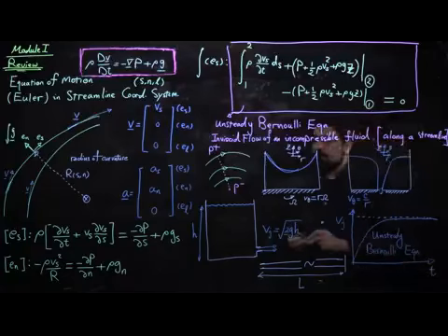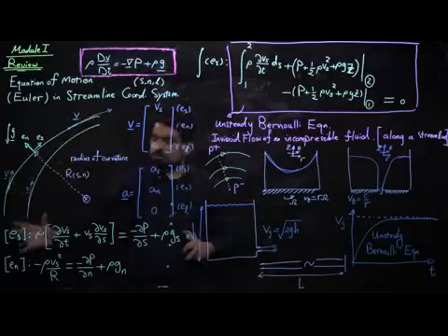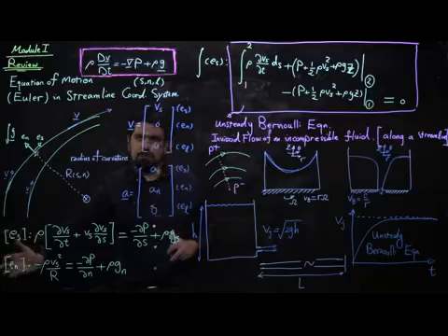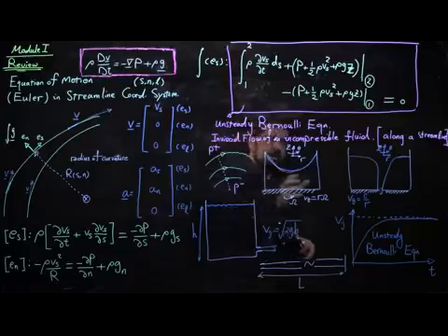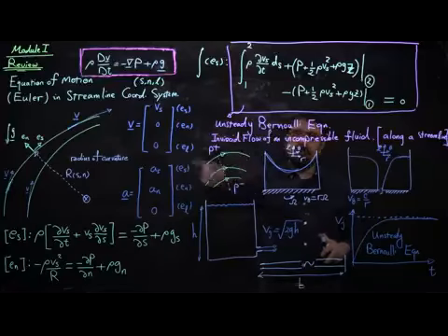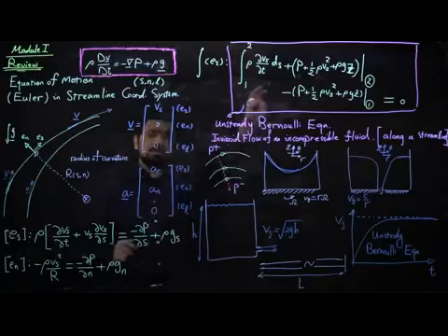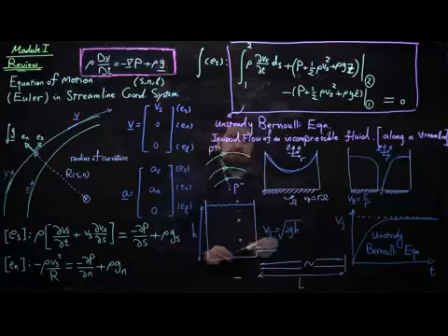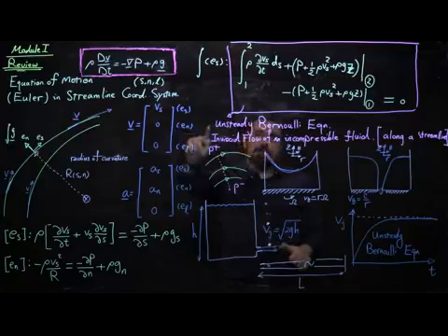So as a short summary, we saw that Euler equation can be used in streamline coordinates in both parallel to streamline and normal to streamline components. The normal to streamline components became very useful in places where streamlines show a certain curvature and there are parts of a circle or maybe a full circle. The Euler equation parallel to streamlines, when integrated, gave us a very useful principle known as Bernoulli principle. Bernoulli principle can be used and it can also be abused. We need to be very careful about the underlying assumptions for this principle.